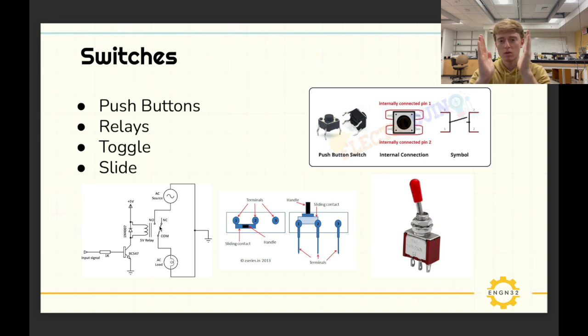Normally closed means that when I'm not turning the electromagnet on, my relay will be off by default. In a normally open system, it's the opposite. If I had my switch normally over here, when I turn the electromagnet on, it'll pop over here. You can have both of those systems depending on how you configure the mechanical design of your relay. But that's what a relay is.